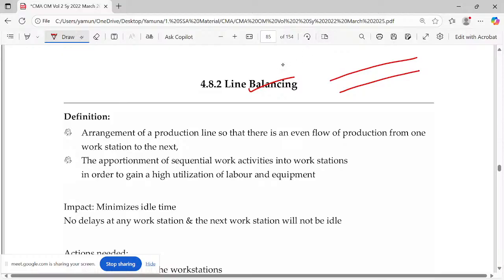If you are checking for Mahindra, it says like 92 stages are being done. That process involves 92 stages. When we talk about line balancing, if you are talking about 92 stages as 92 processes, it's not going to happen as a single process. The unit will come, the belt will be moving in such a way. The unit will come. Probably it will stand here for some 3 minutes. In this 3 minutes, whatever the processes are needed to be done, everything will be done.